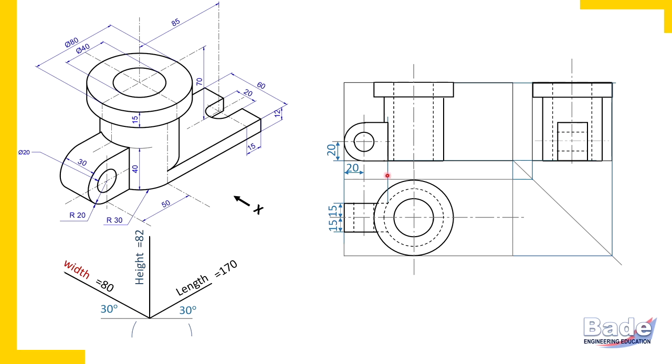So this is how the U-shaped block is complete in all the three views. Now let's focus on the plate. Its largest surface appears in the top view, and in the front view and in the side view it appears as a rectangular strip as usual. So let's focus on this plate in the top view.